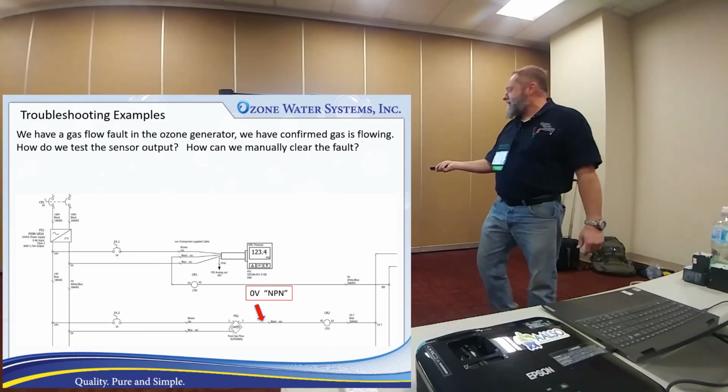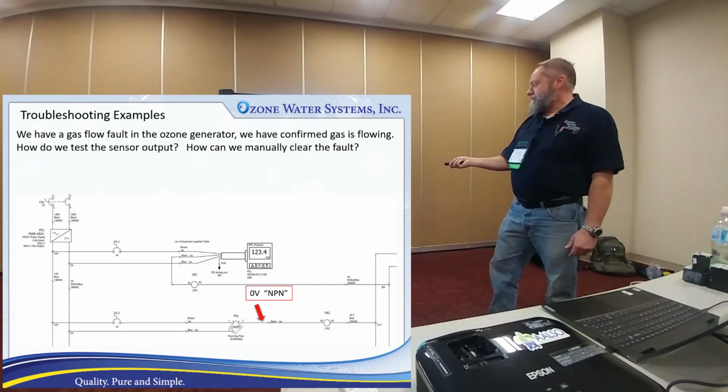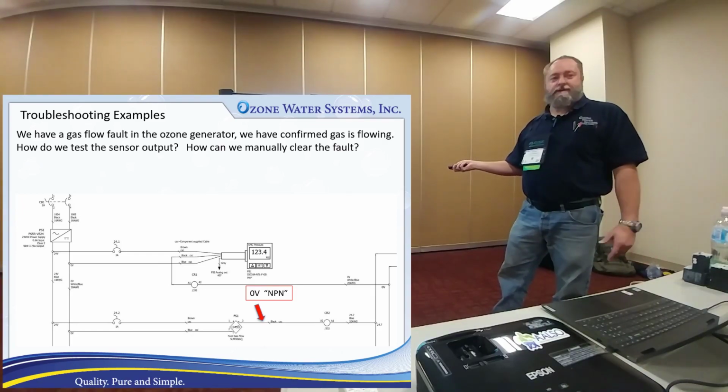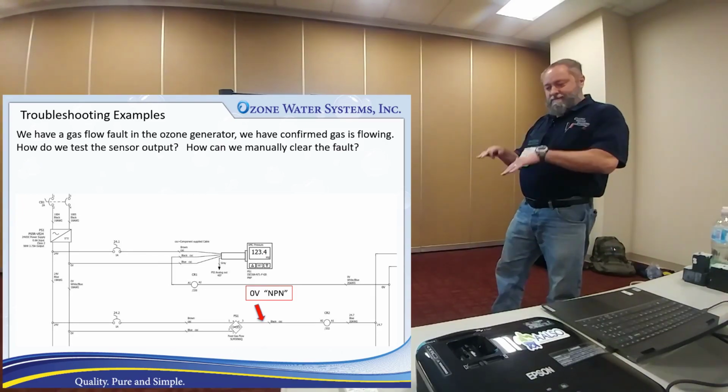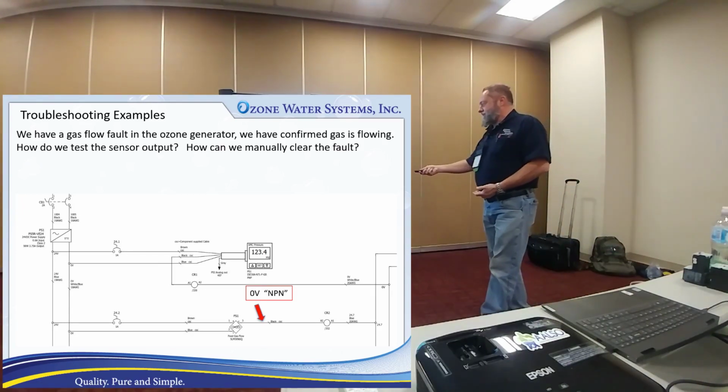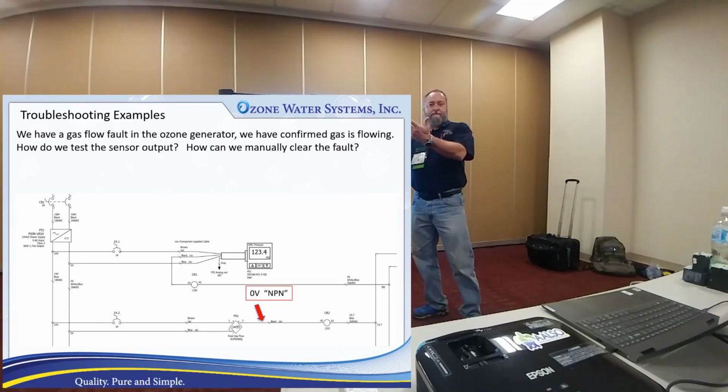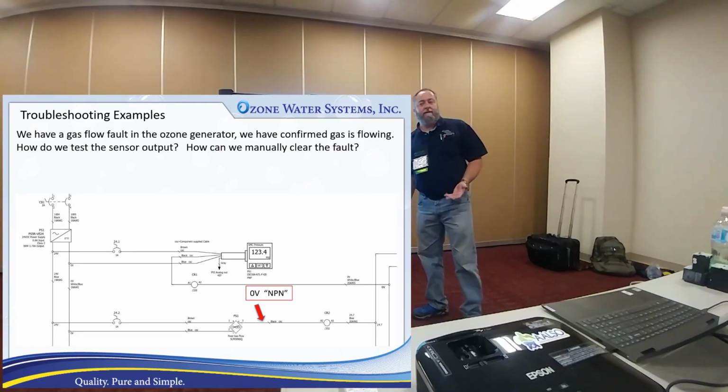You can't see it from where you're at, but we should be getting 0 volts coming out of this when the thing's turned on. Getting a little more to the basic things that you would first check. I mean, there's a couple of LED lights on the thing. Let's look at the sensor, see if it's got the lights on.